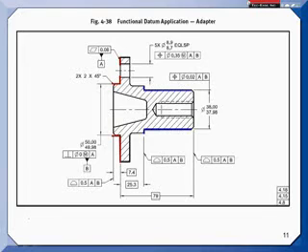Is there much lost by losing the minor or major diameters instead? Well, I remember being at a company that did some measurements on this. It was an inch 1/4-20 thread. They wanted to help out production, so they put a tolerance on and called it out as minor diameter.